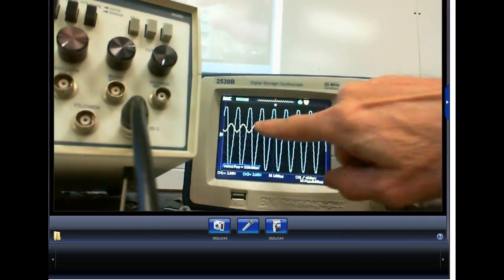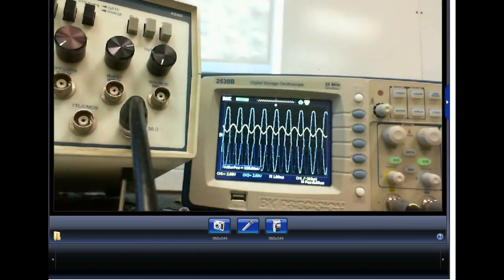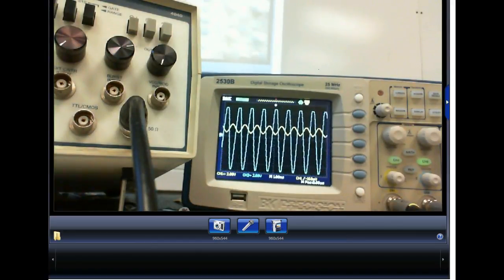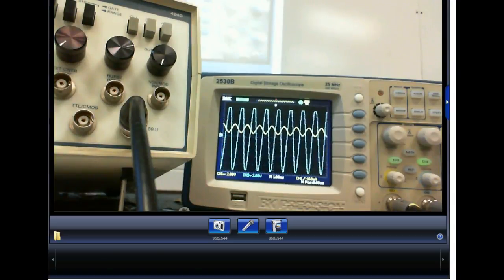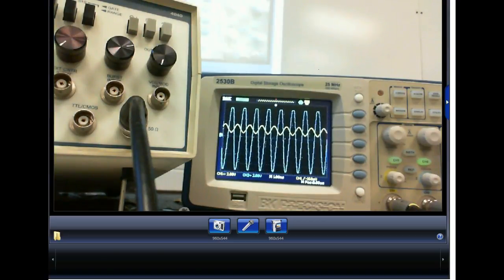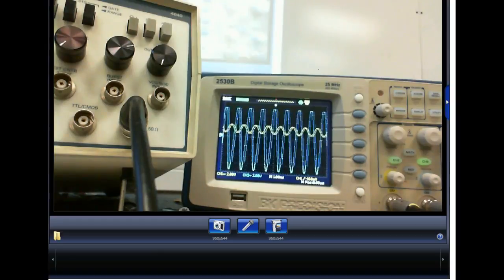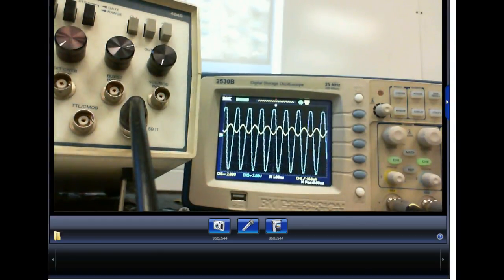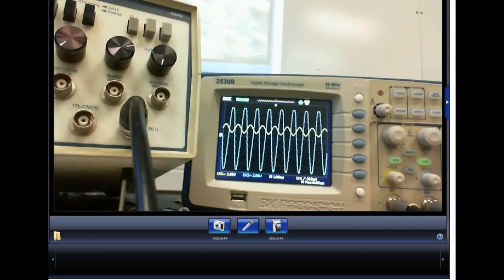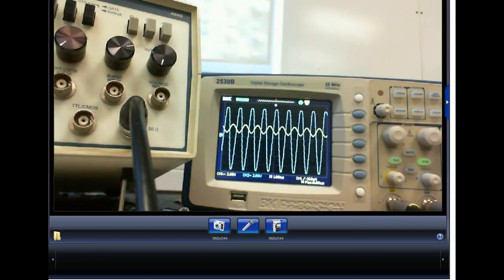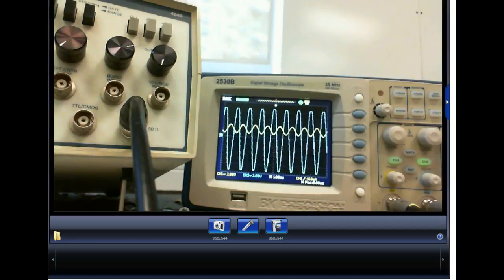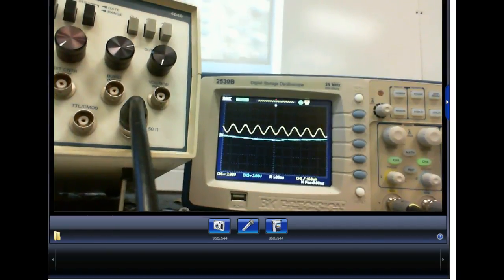So you can see the input signal is actually riding up on that DC bias, and that's what we're doing. Our input signal is varying the DC bias, right? You understand? And then of course, if it varies this DC bias, it affects the voltage drop across RE, which changes the current flow. And if I look at the output, which is going to shift way up, so here's actually the output of the transistor.